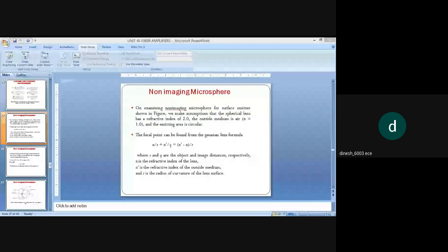So when the radius of the emitting area is larger than the fiber radius, no improvement in coupling efficiency is possible. So in this case, best coupling efficiency is achieved by a direct method. If the emitting area is larger than the fiber radius, we can go for a direct butt method. So based on the theoretical coupling efficiency as a function of emitting diameter as shown, an optical fiber having numerical aperture 0.20 and 50 micrometer core diameter is best. So next is the laser diode to fiber.